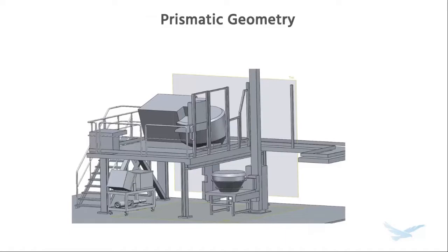We're in this paradigm where the dominant way of expressing shapes is to describe the steps they took to become that shape, mainly by extruding, sweeping, cutting, and other simple commands. And that method of expressing shapes lends itself really well to prismatic shapes like the one shown here, or the bracket, or an engine block, shapes that consist of planes and cylinders and cones and other standard features, or what we might refer to as primitive shapes, or simply primitives.